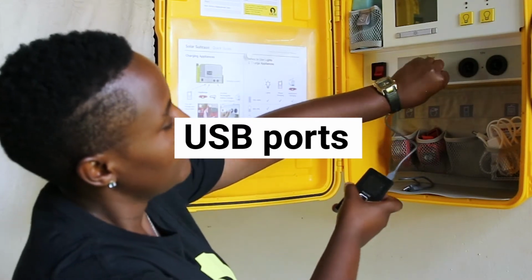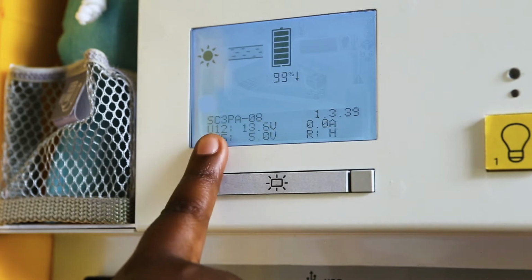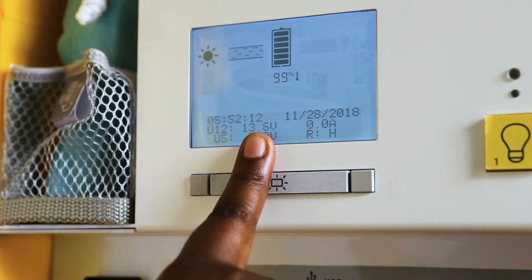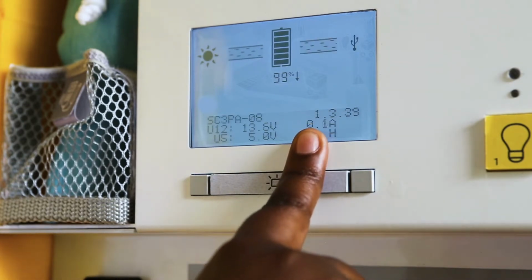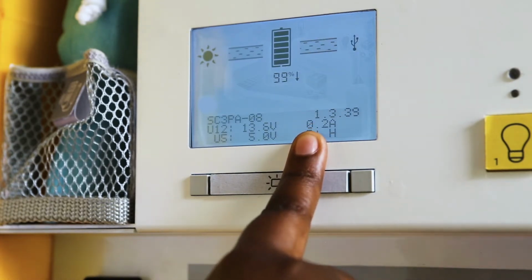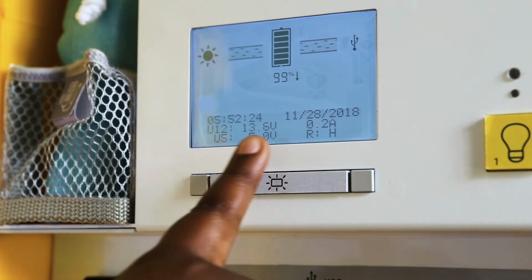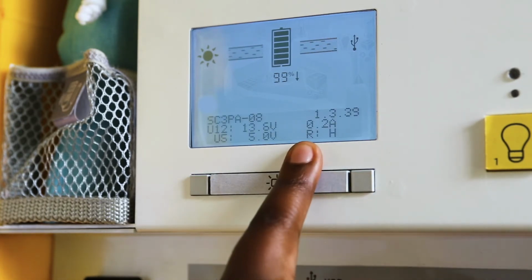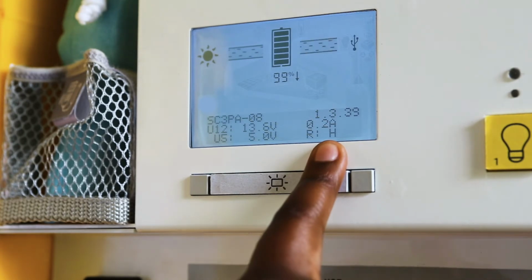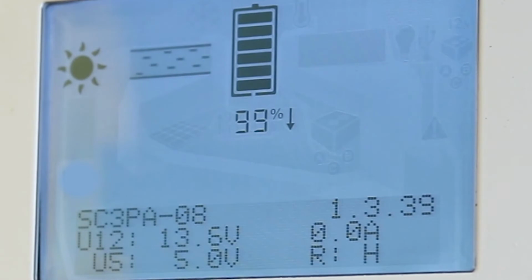USB ports. U12 shows the voltage feeding into the USB port's circuitry and the current being used. It should be around 13 volts. The current will increase when a USB device is plugged in. U5 shows the actual voltage available at the USB port, usually at about 5 volts. And R indicates the USB charge rate, which can be high, H, or low, L. This adjusts depending on how much power is available in the main suitcase battery.